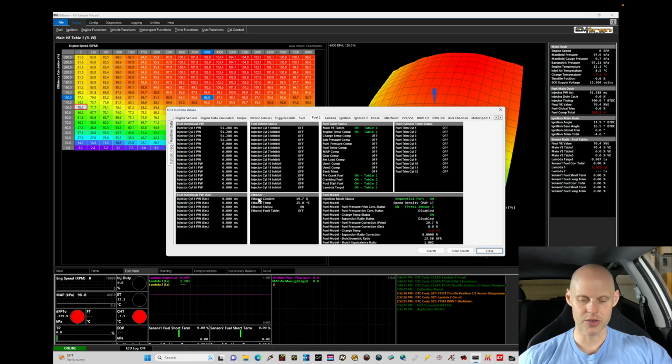We can see the ethanol sensor, which we've set up on our digital input 2. We can see that that's showing the ethanol content of approximately 19.7%, and the ethanol temp is 25 degrees Celsius. So looking at this, I don't know if that degree Celsius here is accurate or not. I'm not worried about fuel temperature, but I am worried about the ethanol content.